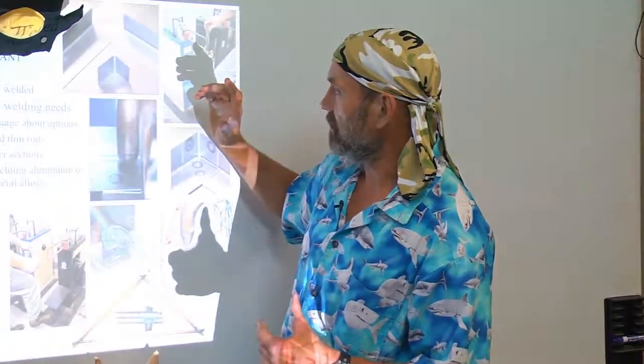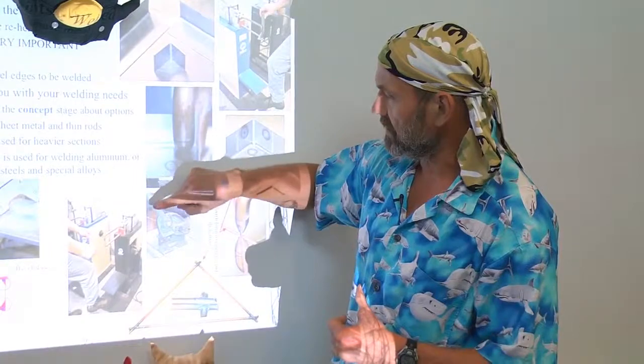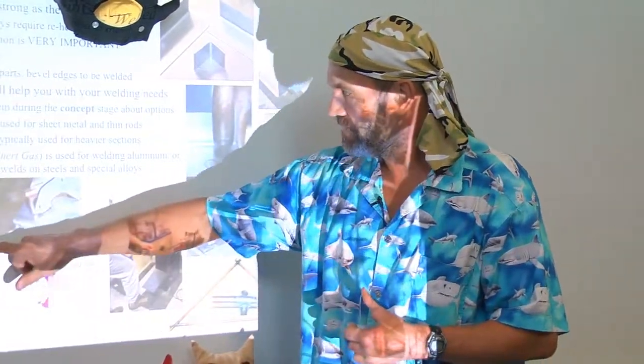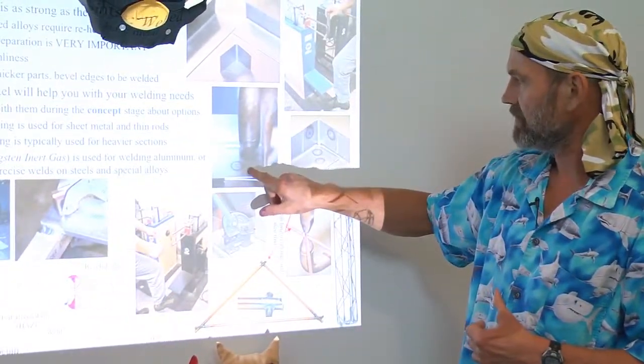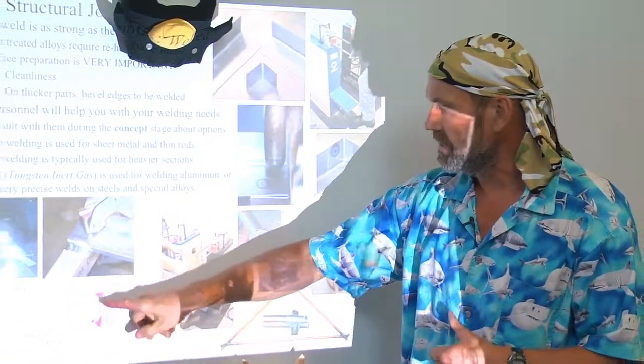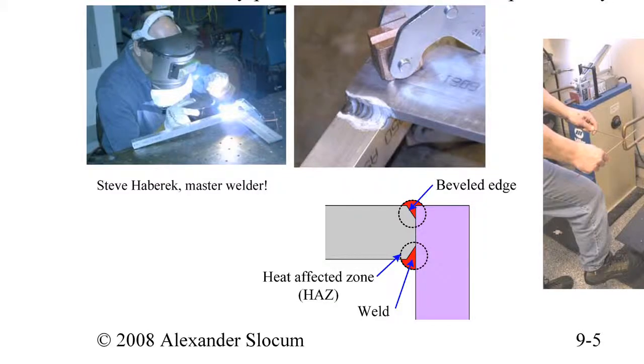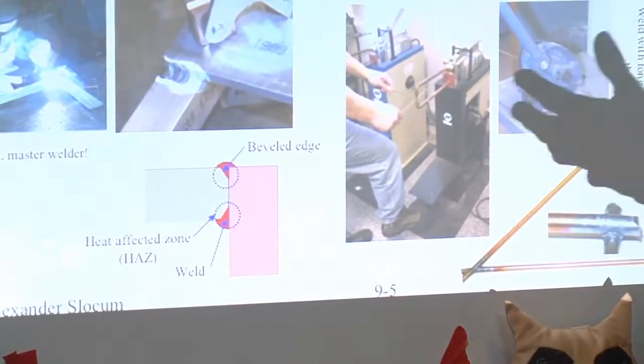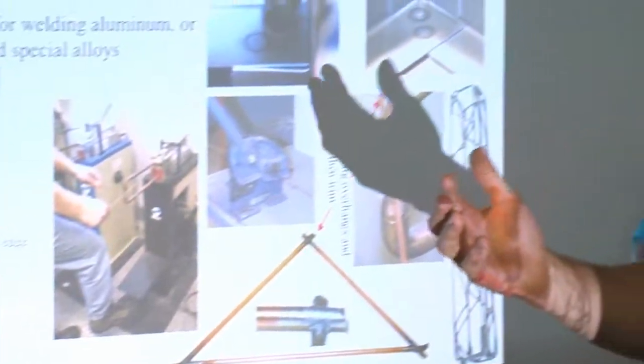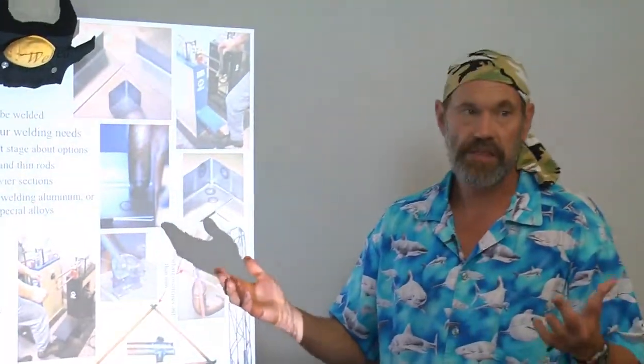Now, one of the things we want to consider when we're welding structures together, manual or automatic processes, is the design of the part edges so they can be welded properly to achieve the proper strength. In welding, you have to be very, very careful: you may specify a high strength material, weld it, and then you can lose a lot of the strength of the material.